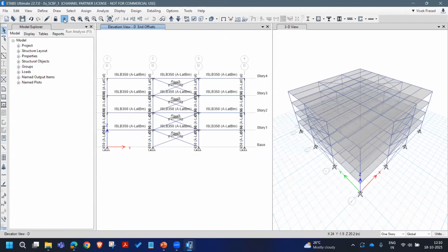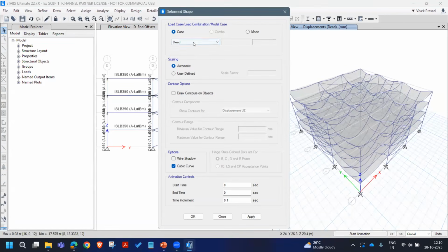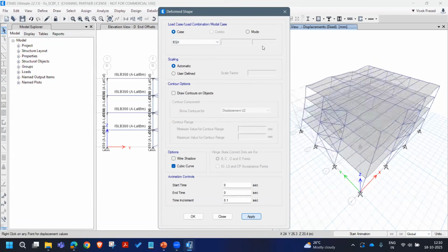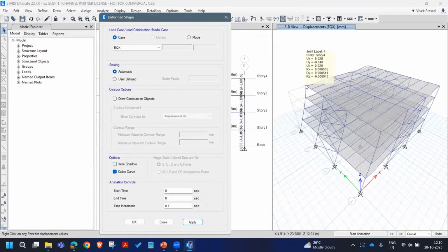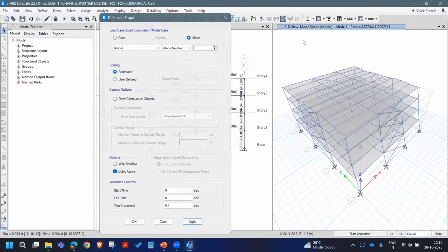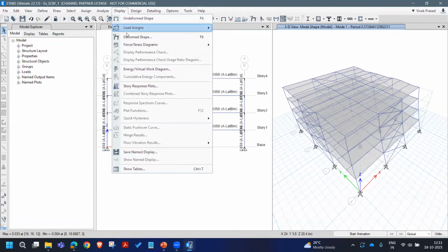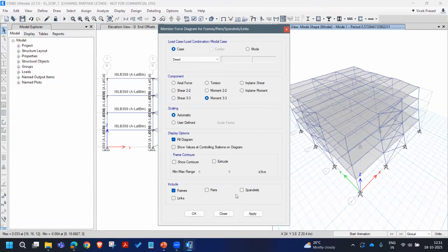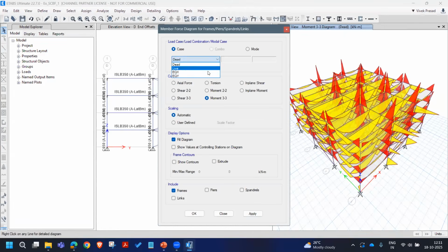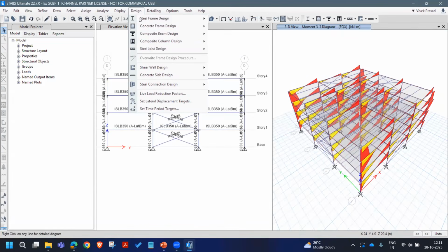Then now we perform the analysis once again. The lateral. Now it is 9 mm. It's reduced as expected because it's less flexible. Time period is 0.57. Right. Now till here, it's the usual analysis that we do, and you can get the frame forces and other things as usual, which I'm skipping, and straight away proceeding to the design of these members.